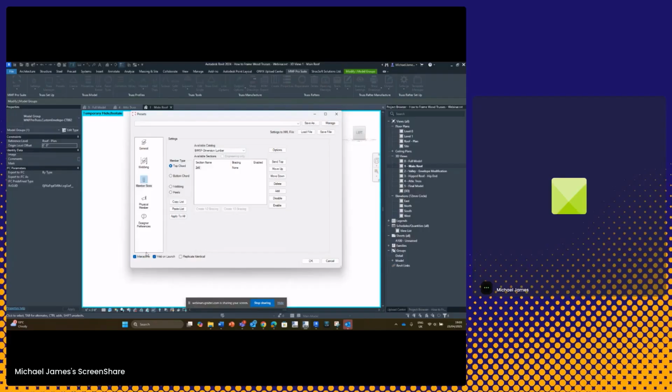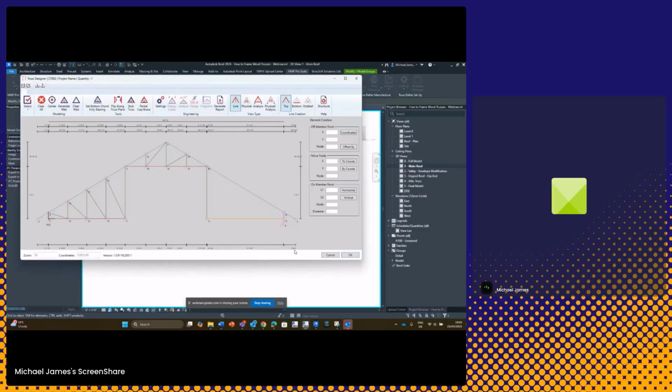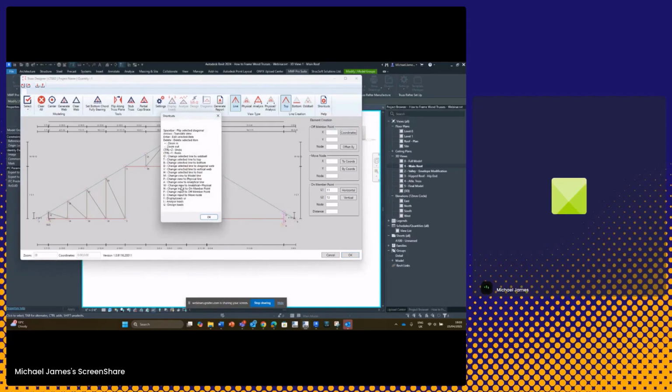All right, so now I want to go into interactive window so we can see exactly what will be placed. It should show us the attic truss. So you can see it's shown here. And I need to define what this member is. Right now it seems a bit confused based on this being the original bottom chord, this being the new one that we added. So I can select a member, one of the manually added members, and I know the code for this one is a bottom chord. So I'm going to type B on the keyboard, and that will allow us to change this to a bottom chord. If you want to know any of the shortcuts, we've got a shortcut option here, which will explain how to quickly carry out any shortcuts if you need to.